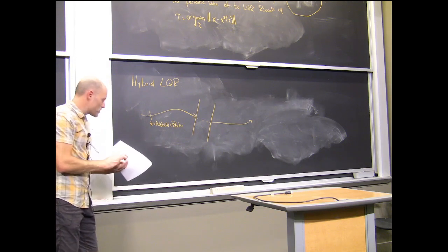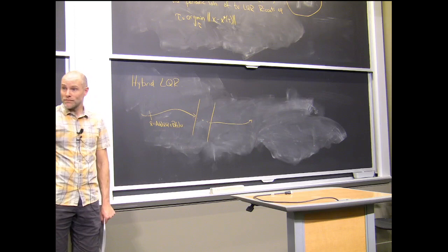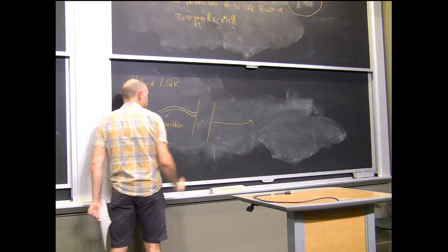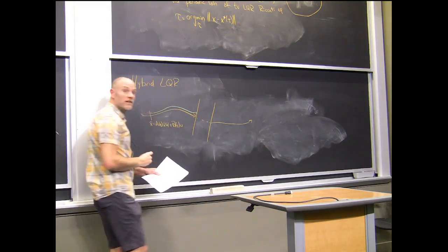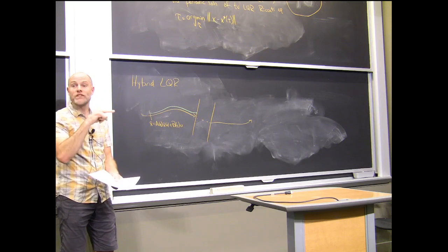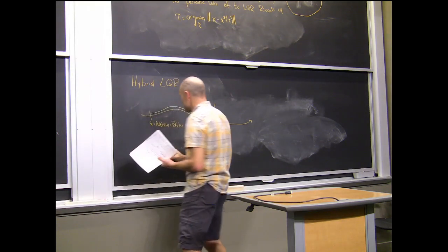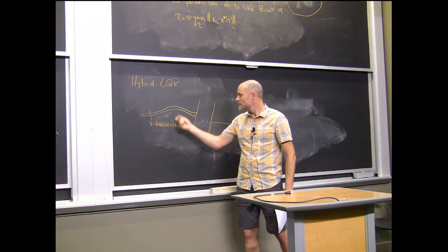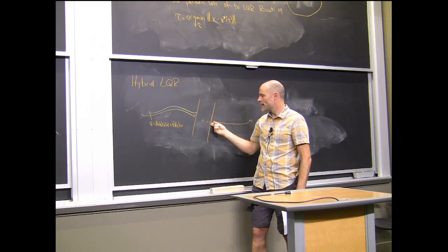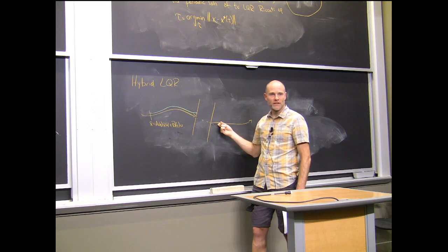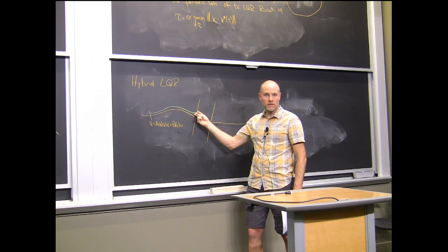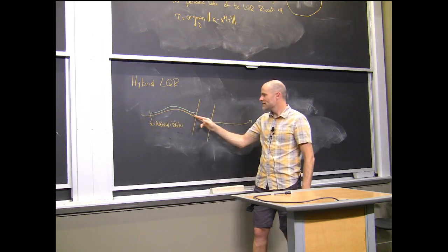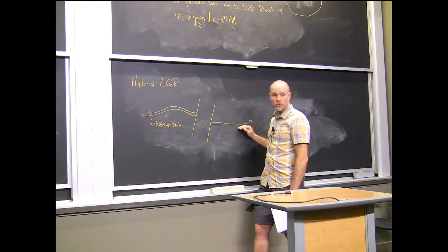In particular, there are lots of squirrely cases, okay, where if I were to clock everything off time exactly on the nominal trajectory, let's say I've got a slightly perturbed trajectory. The time that it actually hits the guard and resets could be different, right? So if I were to design my original time-varying LQR controller through a hybrid impact, and I came up with a K as a function of time, I could find myself in a situation where the nominal trajectory had an impact. It says start using the A's and B's over here, but the actual system lagged behind. So the gains that I could use here might be a very wrong gain to use over here. Did I say that well enough? Right? If you just clock your gains off of time on the nominal trajectory, you might be sad, right?